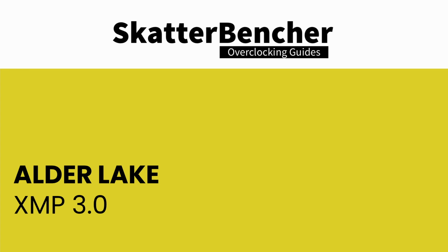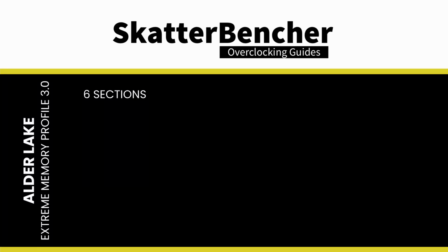Intel Extreme Memory Profile 3.0 is the new XMP standard for DDR5. It is still largely based on the XMP 2.0 specification, but it has a couple of additional features. The XMP 3.0 standard is designed with 6 sections. One global section describes the generic data, which is used across all the profiles. The other 5 sections are designed for 5 profiles respectively.